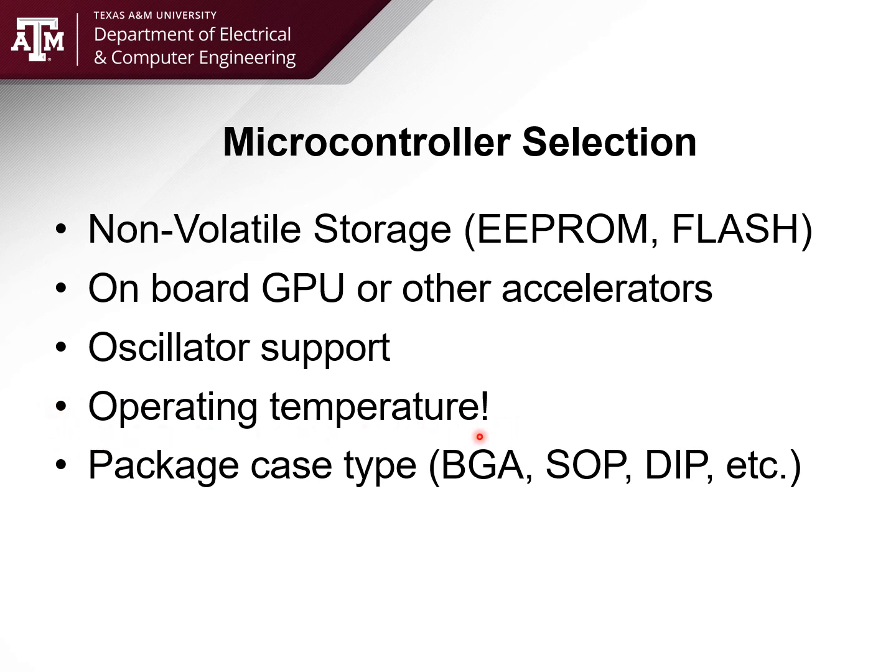I know I've mentioned this several times with transistors and things like this. Operating temperature is key. You don't want to design a microcontroller solution that is only good for commercial temperatures, but it's going to be an industrial temperature solution. In other words, something that's rated for 0 to 70 is fantastic at room temperature, but it's not going to work very well if it's exposed to minus 50 degrees Celsius. It's going to be out of tolerance.